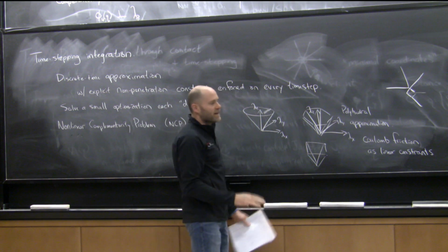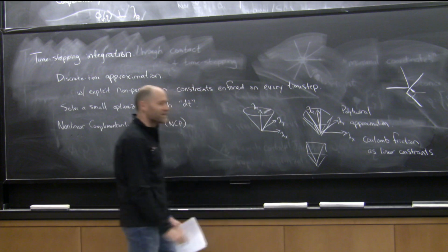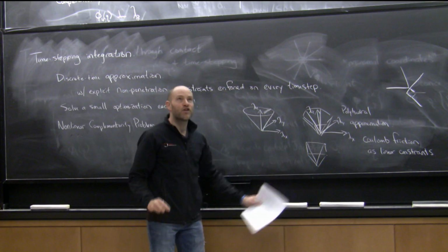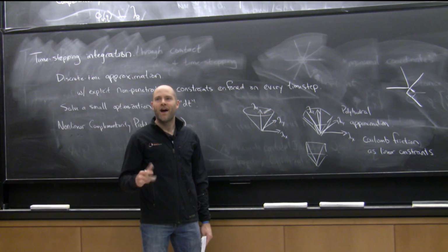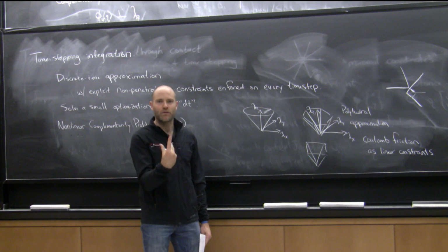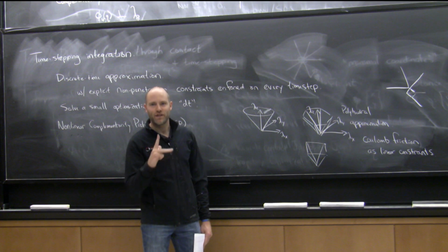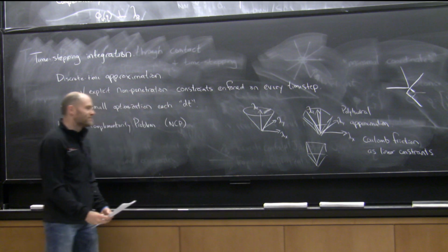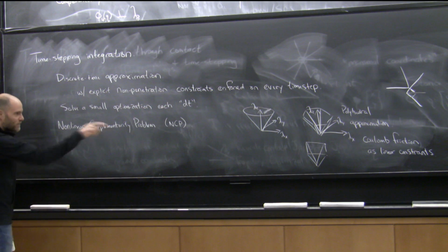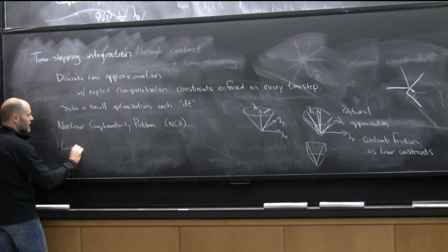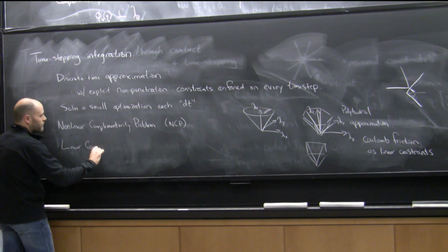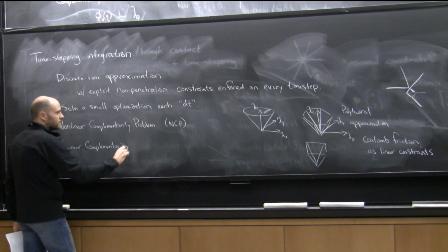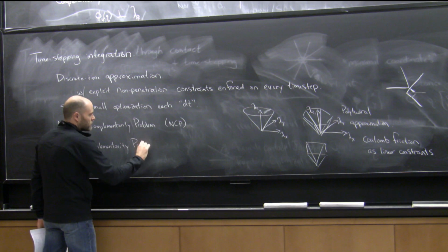And I don't know, the more you dig in, it's a sort of gross approximation. Because what does that mean? That means that your dynamics are somehow dependent on the coordinates you happen to pick to represent your friction cone on the ground. You just change that and your robot will move a different direction. Yeah, it's gross stuff. But if you make that approximation, then you get a linear complementarity problem. And this is the stuff where there's lots of good work in optimization.